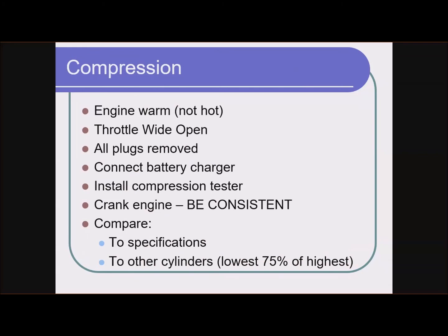Now with electronic throttle bodies, on a lot of vehicles, you have to use a scan tool and put the vehicle in compression test mode. And what compression test mode does for you, it will open the throttle, it will disable the ignition and the fuel injectors. So it's actually kind of convenient, but you have to know about it. In a minute, we'll go on all data and we'll look up for a particular vehicle the compression test procedure, and I think you'll see that it's one that you use a scan tool for. Now, in an older vehicle, you don't have that option.